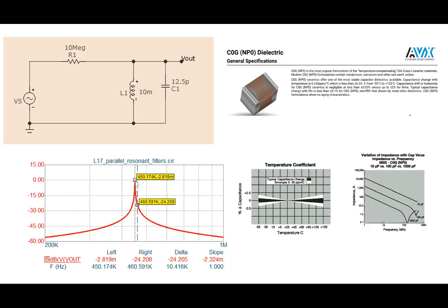And so as I'm saying, you may start off and switch on your radio and it's tuned to 450 kilohertz, and then after a while, as your radio heats up, you find that the signal fades away. Then, in olden days especially, one would fiddle around with the variable inductor or capacitor and retune the circuit. That is a problem, especially if you have a high Q circuit. A little bit of detuning will cause a huge change in the output.